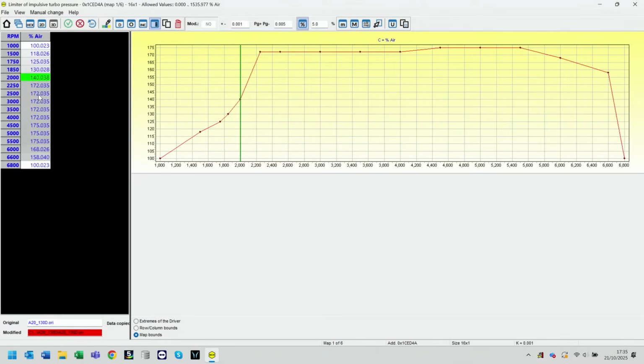So we're going to be respectful of that, and our changes will start around 2,250 RPM on this vehicle and build to our peak torque, which would be around 4,000 RPM. Now this is a little bit higher in the RPM band than we would typically start. It would usually be around 1,800 to 2,000 RPM on most gasoline turbo cars. But this is a great example to show why you may differ from those standard rules because of data inside